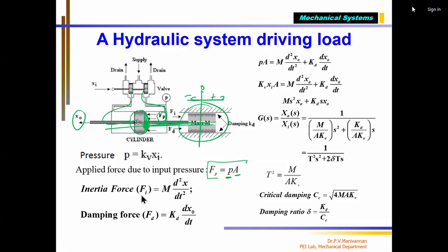So that's why now we know that there are additional forces acting. Now we added a mass. Till now we never saw it. Please note, as you ask the right question, even this piston has a mass. We did not consider this in the previous equation. We were talking in terms of just displacement and pressure. But in this case, the load mass is heavier compared to the piston mass. The load mass may be very heavy, that's why we cannot ignore it. And that's why we put the inertial force due to the mass.